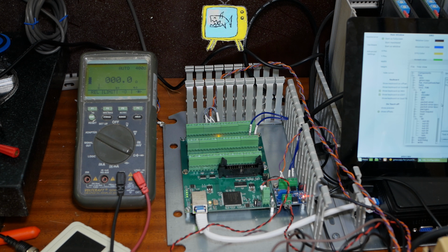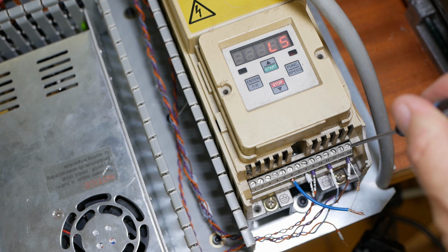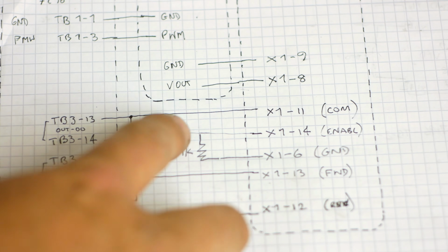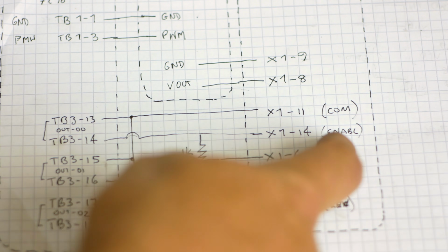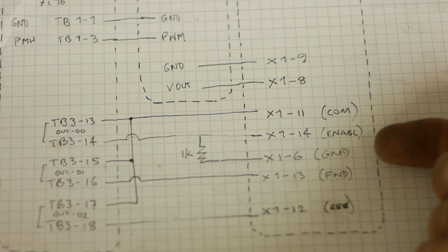I'm guessing that there's enough current flowing to still activate the VFD's enable function. I did a bit of internet surfing and I thought maybe it needs a pull down resistor. So I've put a 1K resistor between the switch output, I guess switch input in that case, and the earth of this device. Didn't change anything. So if anyone's got advice of how to fix that, I'd appreciate it.